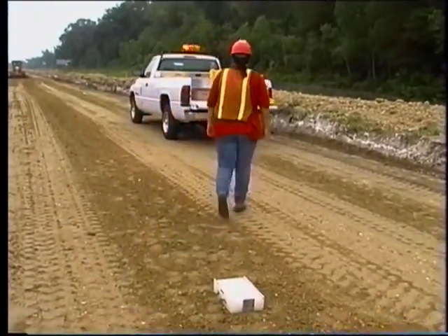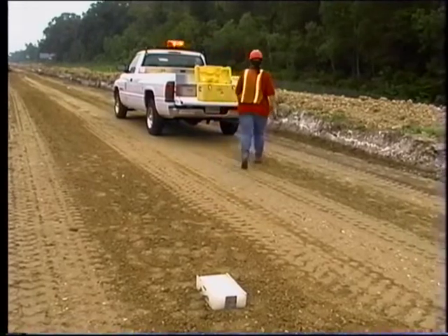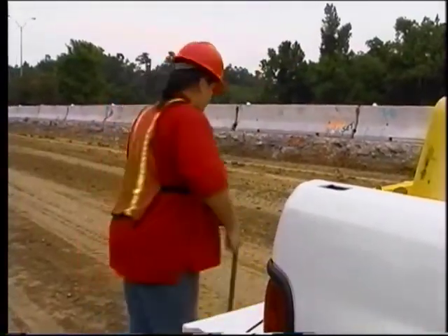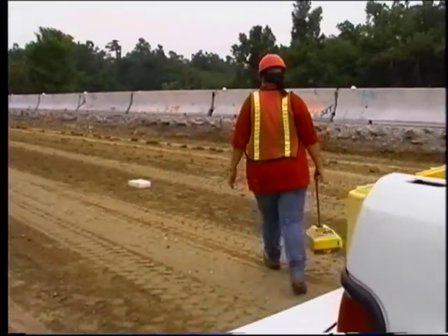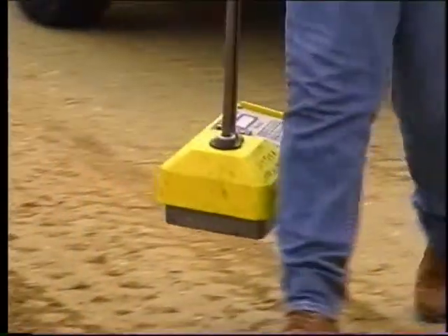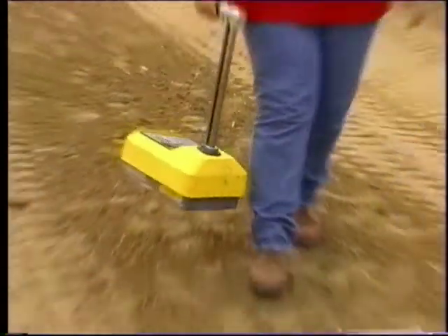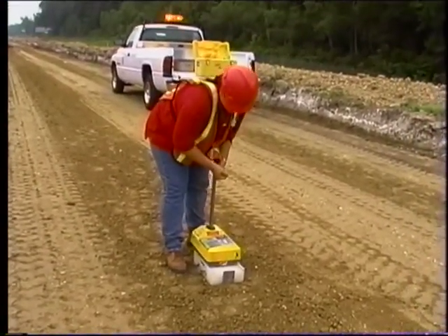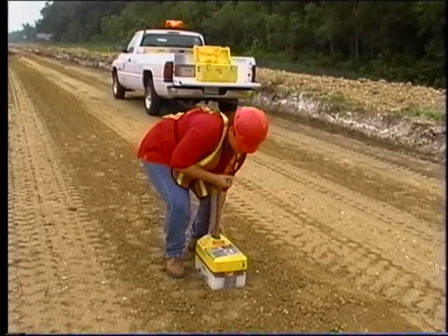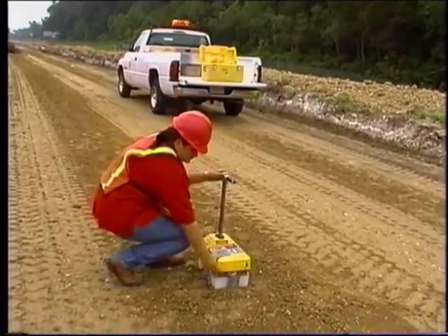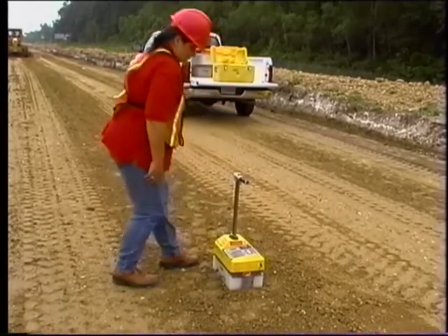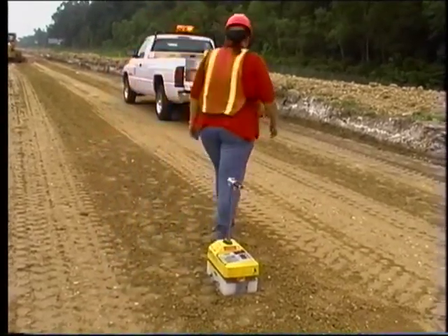You take a standard count once each day when the device has been idle for 4 hours and when you suspect that the test results may be wrong. Once you have a correct standard count, you don't have to repeat the procedure if you test in another area. As long as conditions are similar and the machine has not been idle for 4 hours, test results are valid. You'll need the device and the reference standard block for this part of the test. The standard count should be taken near the site where the actual test will be taken.